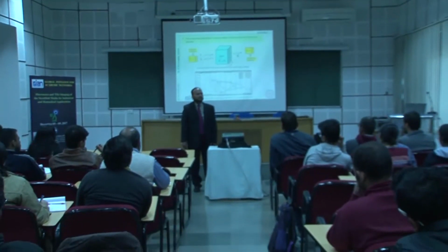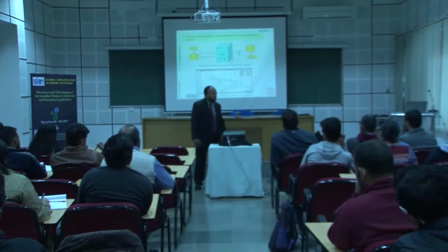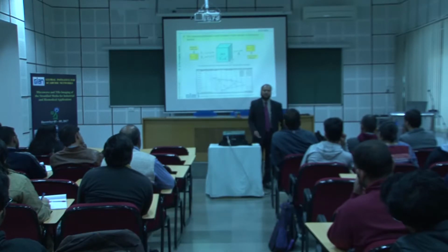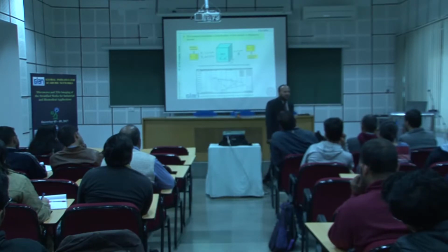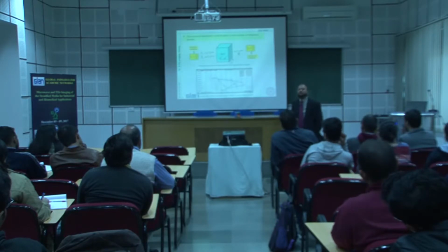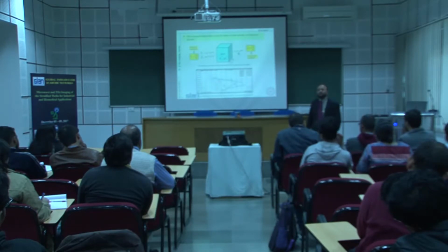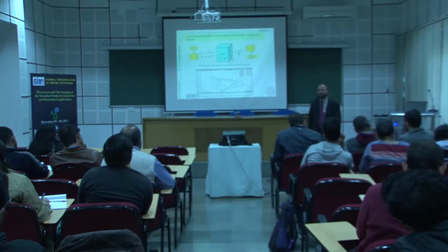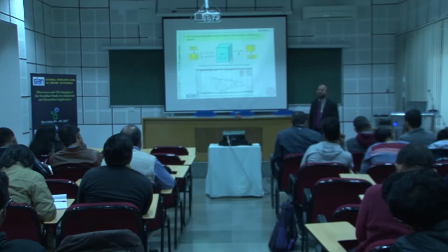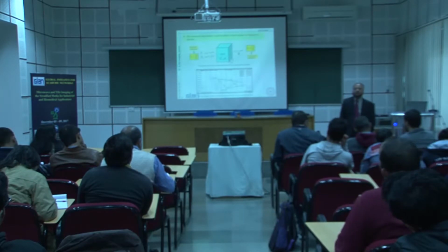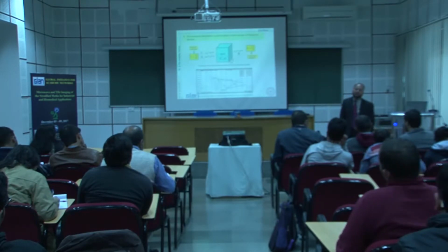Wide bandwidth. The main simple thumb rule is that the wider the frequency band, the narrower the pulse becomes. So ideally you would have a very wideband antenna along with a wideband network analyzer, and then you can have a very narrow pulse. And the narrower the pulse, the better the resolution in the space domain. That's why, if you can measure over a very wideband, it leads to very good spatial resolution.